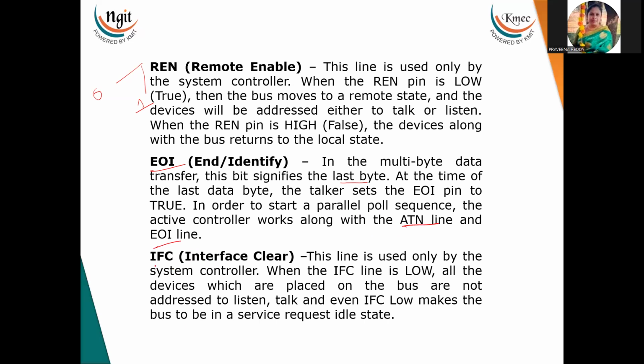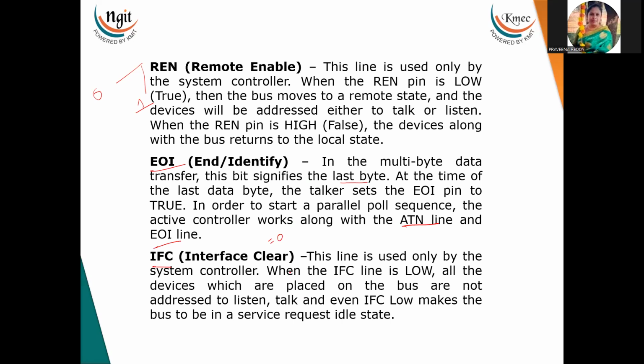Next one is IFC, interface clear. By making this line equal to 0, the total bus can be reset. At that time, the bus will not address the listener and talker. So the bus will be reset. Now this is about the IEEE 488 protocol.